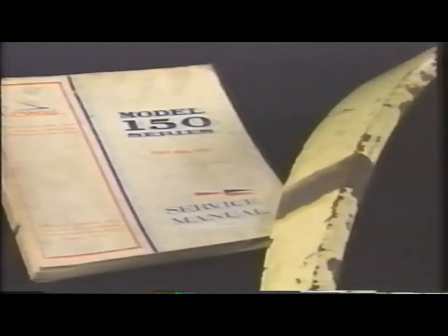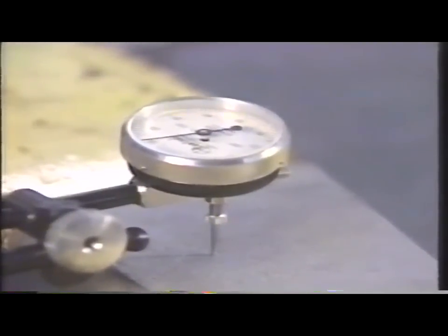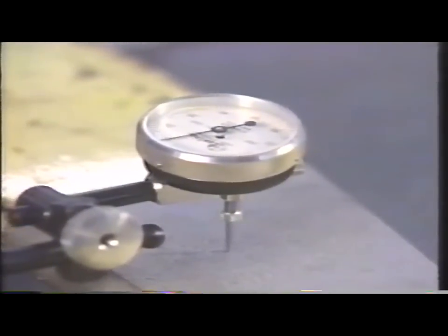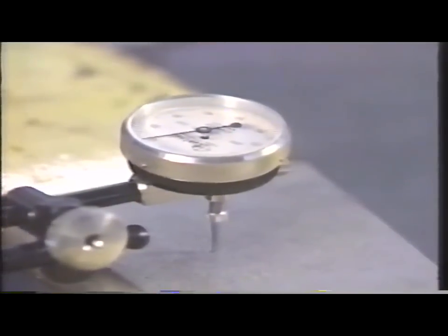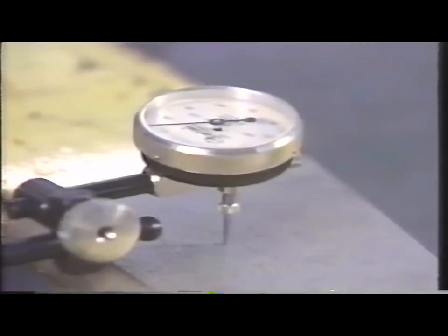The manufacturer's repair manual will give the maximum amount of material which can be safely removed from a part or panel. If not, contact the aircraft manufacturer. You can use a depth dial gauge to measure the depth of the corroded areas. To properly use this tool, you will need to take readings both in and around the corroded area.